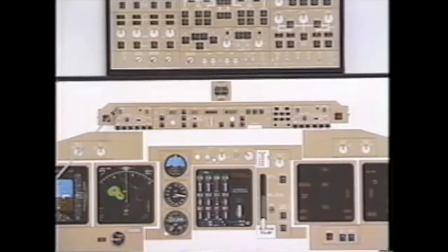To change the display, specifically for decision height or MDA, select the mode in which you wish to deal with. The small knob on top increases or decreases that value. To get rid of a decision height, select decision height and turn it counterclockwise to indicate something below 0. This will blank the radio altitude display. To get rid of an MDA, select MDA and turn the selector counterclockwise below minus 100 feet to blank the MDA display.